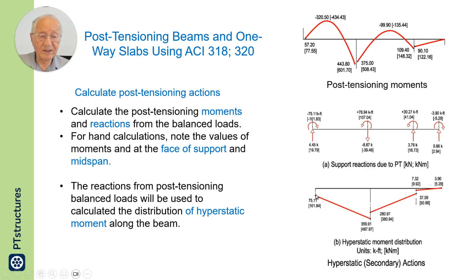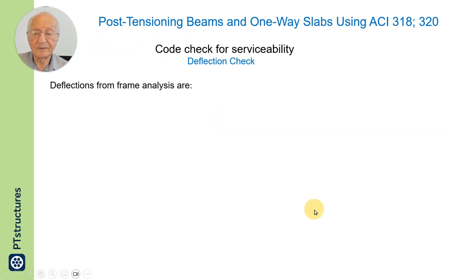Here, this bending moment is the same as this bending moment. And here, this moment is equal to these actions multiplied by this distance. This is how I form the bending moment diagram of hyperstatic actions.